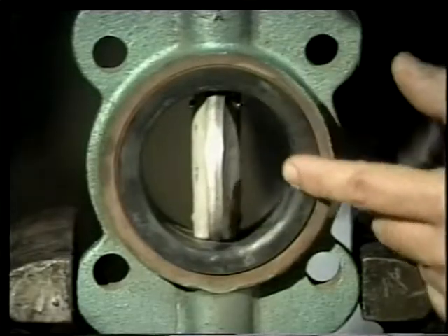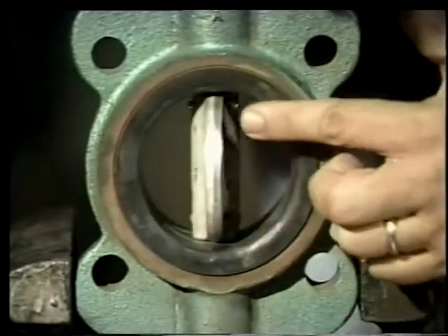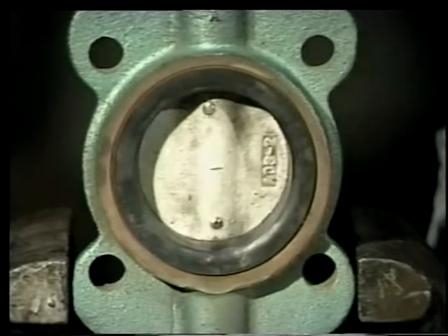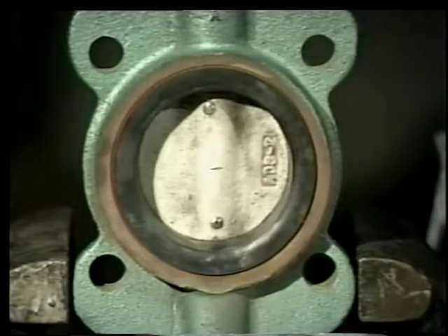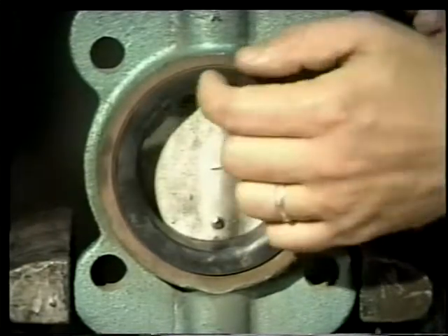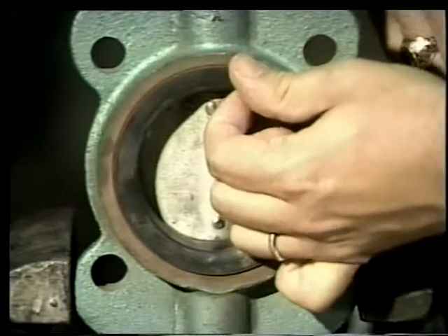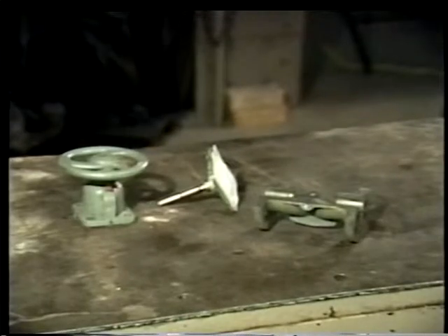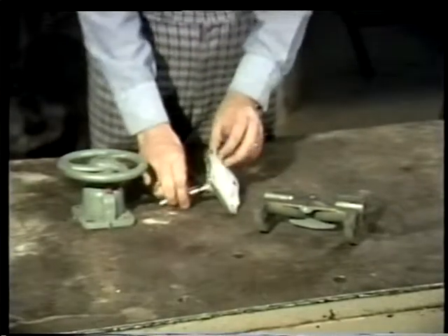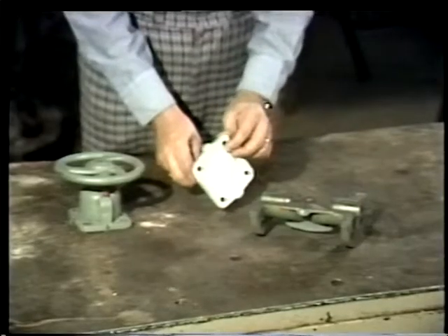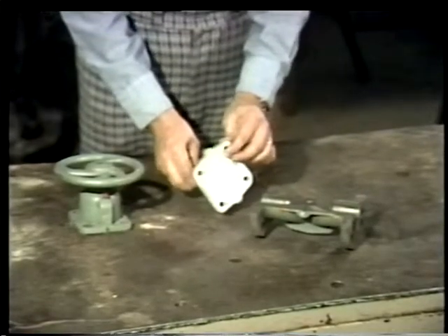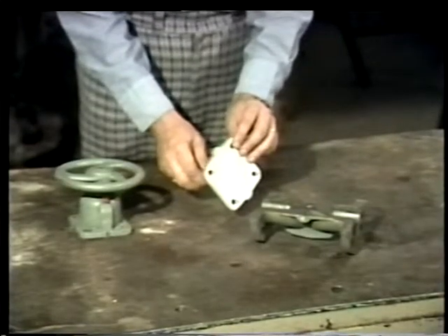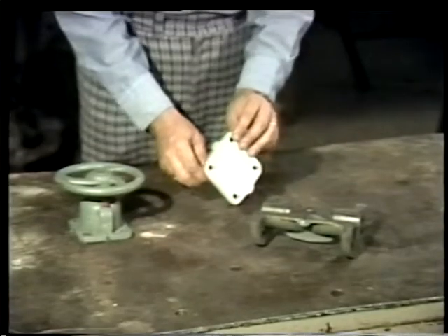A resilient natural gum rubber is used for the seat of most butterfly valves. This provides a firm fit and tight seal when the disc closes on the seat. The gum rubber seat can't easily be nicked, and it'll fit into any small indentations on the seating surface of the disc. Another type of valve with seating surfaces made of flexible material is the diaphragm valve. Now, the disc on a diaphragm valve is made of rubber, neoprene, or soft plastic. This type of valve provides very good control and sealing qualities in systems that carry abrasive or corrosive fluids.